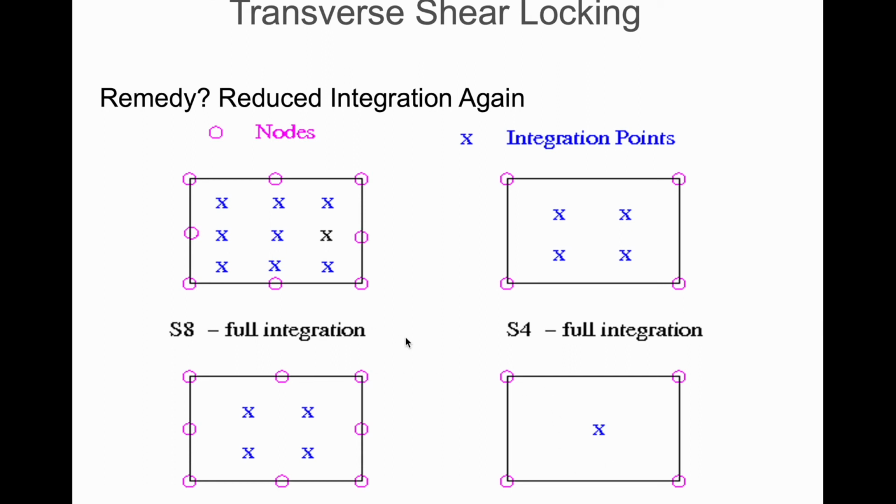Here, this is represented by the shell element. So you have here the fully integrated shell element. So the shell element is like a 2D, but you can have a 3D behavior by having 3 degrees of freedom for every node, so X, Y, and Z, plus rotation on the node. So we are also still going to address this on the classes. So we have here the fully integrated version of the 4-node shell and the reduced integrated version.